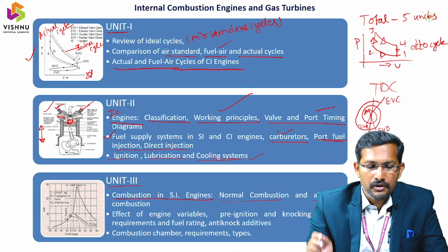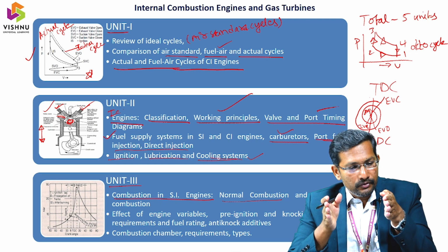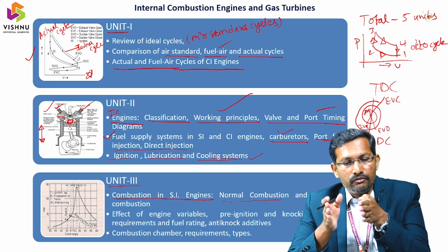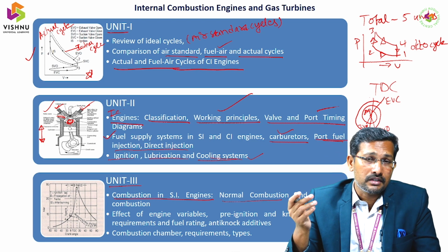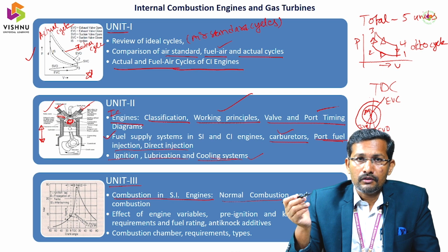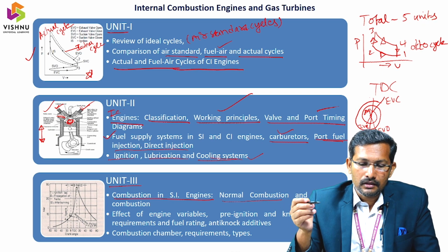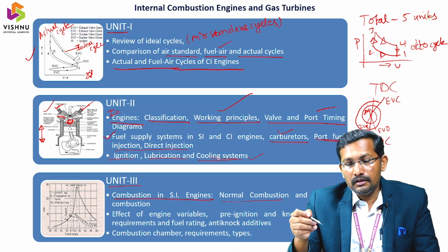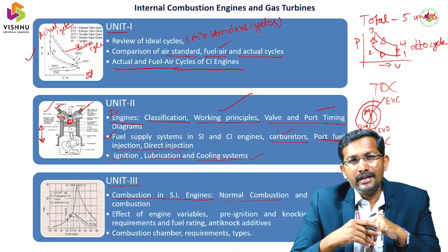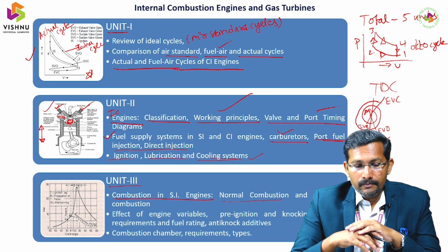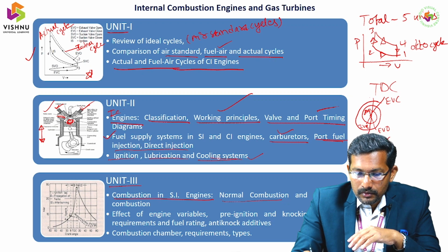But in abnormal combustion, instead of moving slowly in this regression way, all of a sudden, midway within the fuel mixture, combustion starts somewhere. Due to high temperature points, because of carbon deposition and such things, combustion suddenly starts by itself. Then these two combustion waves collide and we get some sound. That is knocking. It is not common; it is abnormal combustion.